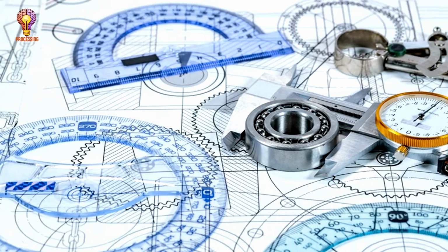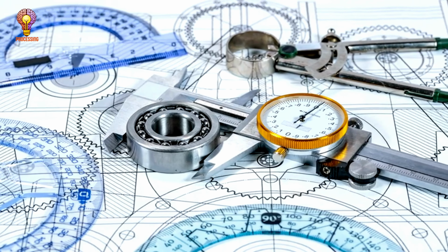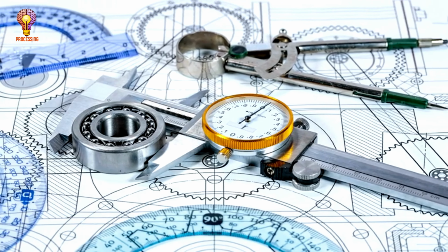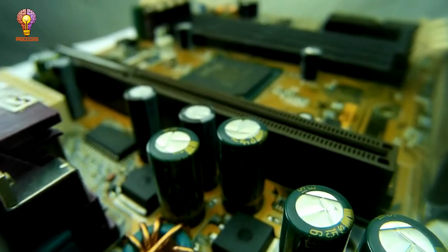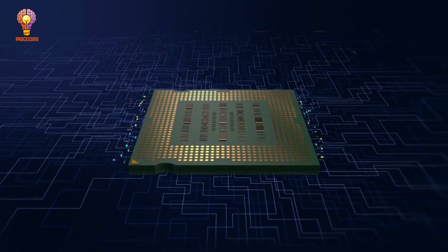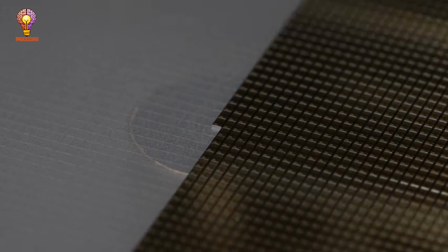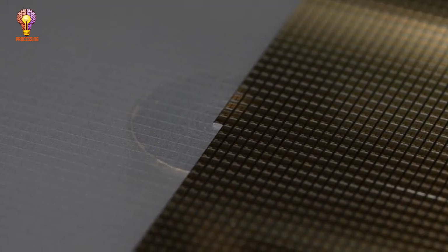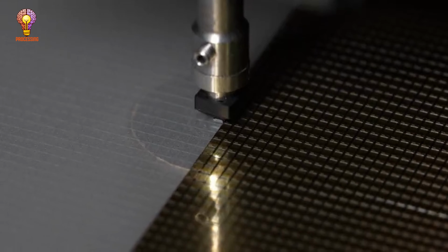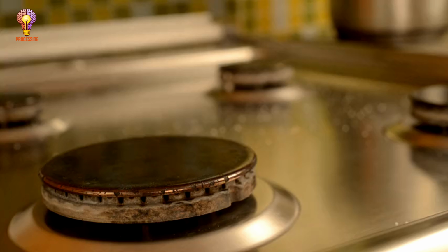1. Concept and design. Before manufacturing begins, extensive planning is required to ensure performance, efficiency, and user experience. The processor, CPU, GPU, is the most complex component, involving nanometer-scale transistor manufacturing. Steps in CPU-GPU fabrication. Silicon wafer production. Pure silicon extracted from quartz is melted and formed into a cylindrical ingot. The ingot is sliced into ultra-thin wafers 300 mm in diameter.